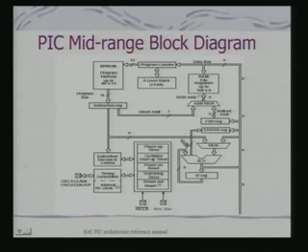This part is primarily the ALU part for doing arithmetic computations. And what is interesting, you will find that this RAM area is also being referred to as register file. Okay. In fact, all these RAM locations can be actually considered as registers. And as I have already stated, a RISC processor will have a large register bank, because it will use the registers for majority of its operations. Here you will find that the same condition is being satisfied for the PIC processor.